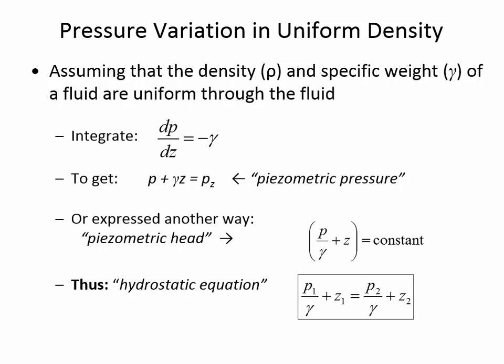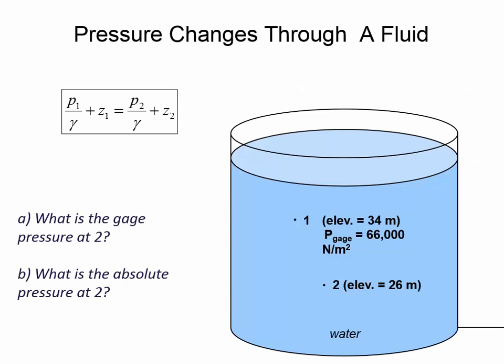So we can use this hydrostatic equation between 2 points in a liquid where the liquid isn't moving. That's the static component of the hydrostatic equation, is what we're talking about here. It can be liquids in different locations even. It could be a tank that's connected to another tank by a pipe, and if the tanks are connected and the water isn't flowing between them, you can use the hydrostatic equation between only points where the water isn't flowing.